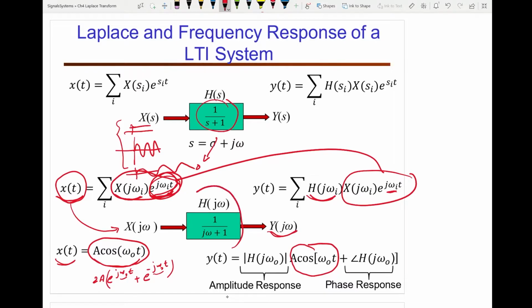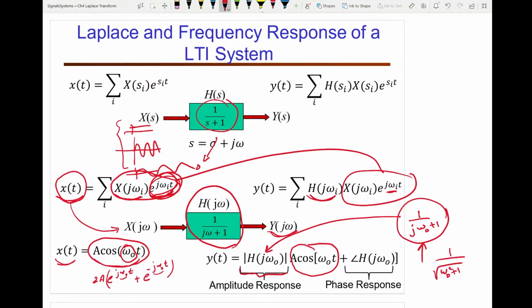And the system responds to this frequency. So I plug in here 1 over j omega 0 plus 1. This quantity has a magnitude, and we call this the amplitude response. And it has a phase, which is...